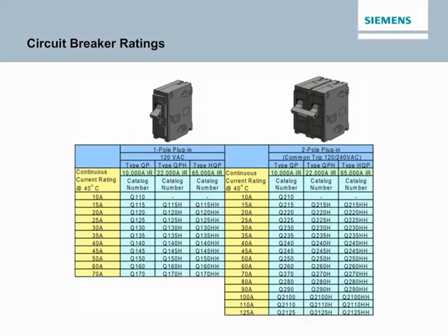Every circuit breaker has ampere, voltage, and interrupt ratings. The accompanying chart shows the ratings for some typical one-pole and two-pole residential branch circuit breakers. The ampere rating defines the maximum continuous current a circuit breaker can carry without tripping. Because the function of the circuit breaker is to protect circuit conductors, the appropriate ampere rating for a circuit breaker is dependent upon the ampacity of the conductors in the circuit. Each circuit breaker also has a voltage rating, which indicates the maximum voltage it can handle. In other words, the voltage rating of a circuit breaker must be at least equal to the circuit voltage.